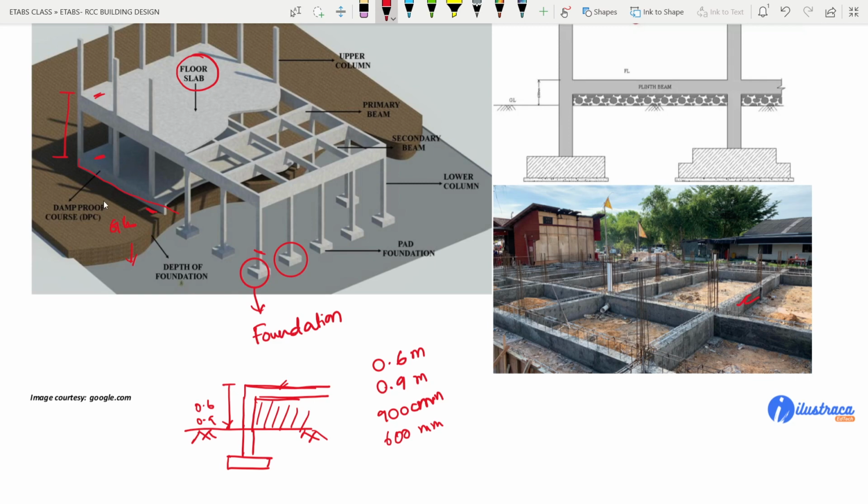So here, as it is above the ground, we consider it as plinth level, or you can say ground floor level, and this is, suppose, the first floor level, floor 1. Okay, and this floor to floor height in case of residential structures we consider maybe 3 meter, and in case of commercial structures it can be 3.6 to 4 meter or more than that. That depends.